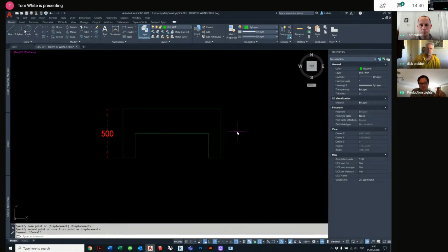Yeah. So we talked about the rename command, I think. So then I'd go back and rename the chair. What's really important is, if I'd called my chair in the first place PLX chair 1, it would have been different. It would have gone straight in. So actually naming blocks and drawings and styles and everything like that is really important. And it's really good, as Dom says, if you're taking over a drawing, you can instantly see where somebody's been and what it all is, from line styles, dim styles, blocks, everything.